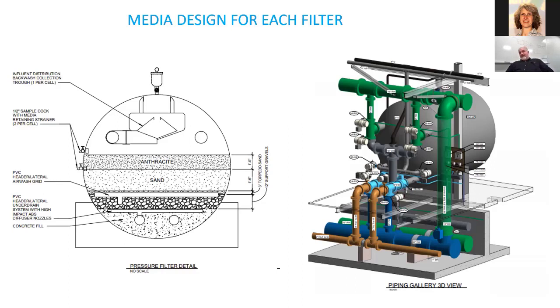We're actually working on it. Water softeners are also an approved treatment technique for removing radium. In the distribution system at point of use, we've got about 90% coverage with softeners now, and we're working on being able to get total coverage, so that we can get notification and approval from the state to be able to re-equip that well and put it back into production.